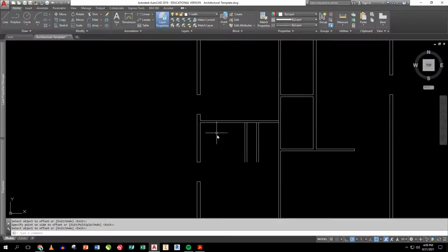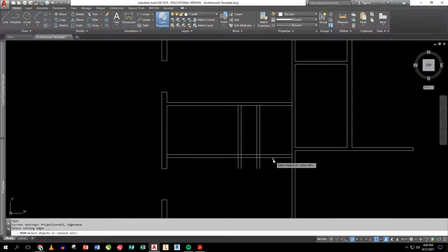It's 5 feet from the outside to the inside. Offset 60 inches from here down. Offset, enter twice, 3.5. I'm going to offset this like so, and then I just need to do some trimming. So I'll trim, get rid of that.